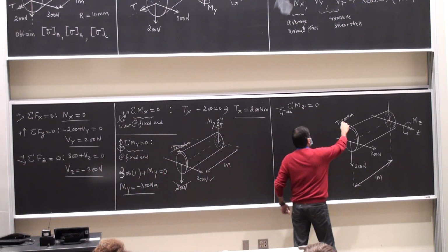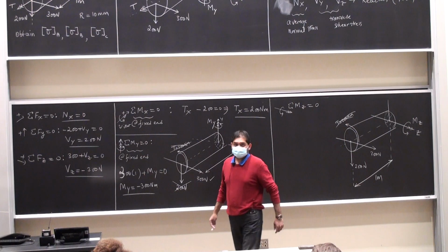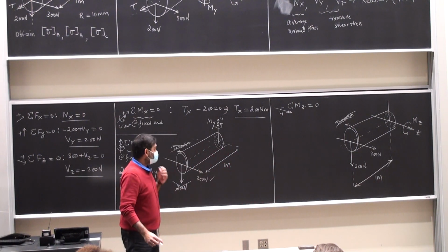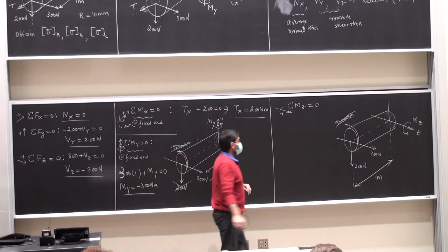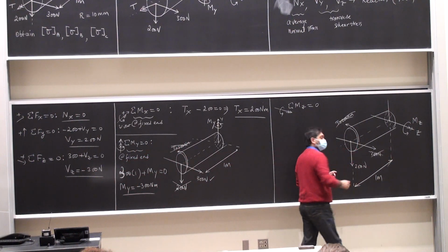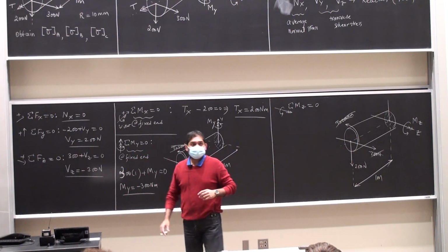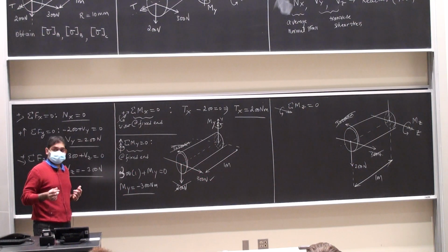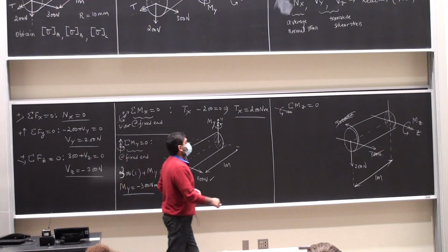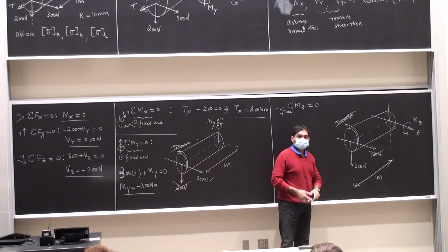200 Newton meter torque, obviously we've taken care of that fellow. Then the 300 Newton force is parallel to the z-axis, so it's not going to cause a rotation as well. So this is also gone. Everybody with me so far? Forces parallel to an axis cannot cause a rotation about that axis. Okay? Which leaves me with this 200 Newton force.